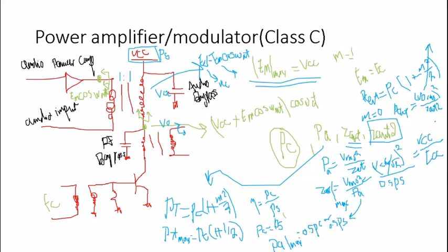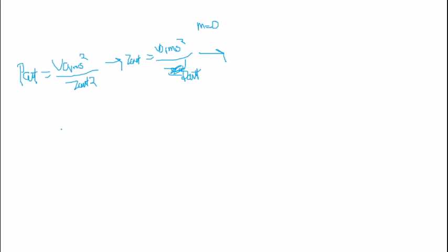So I'm going to move to another slide. Continuing on an empty slide, here we found that the power of the output equals the voltage at the output RMS squared divided by our desired Z output, the impedance at the output that we're trying to find. Rearranging this gives us the voltage at the output RMS squared divided by P output.